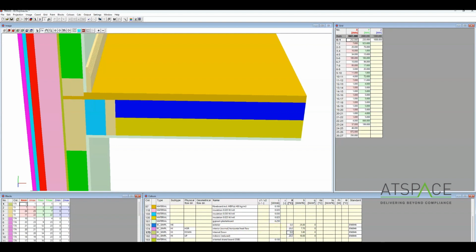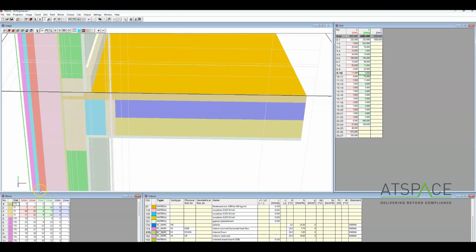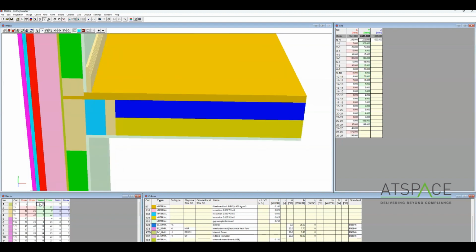Then we can set the temperature to 20. All the rest of that is correctly set up. So now we just need to put that boundary in its proper place. So we remember where we've created that new grid section for the boundary condition on the y-axis. It's 9 to 10, and that's that 1 mil section there. So what we're going to do down here is just put 9 to 10 there, and that's given it the correct height.